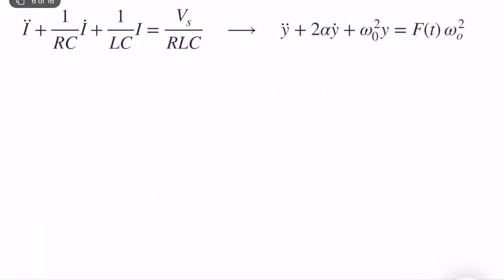Now again, if you remember from ODE classes, let's assume that I of t, which we were trying to find, is composed of two parts: homogeneous plus particular solution. We already know how we can figure out the homogeneous solution, right? Because based on alpha and omega, we have three cases: overdamped, critically damped, and underdamped, and we write that. The only thing that we need to compute later is C1 and C2, which come from the initial conditions. But now we have a particular solution.